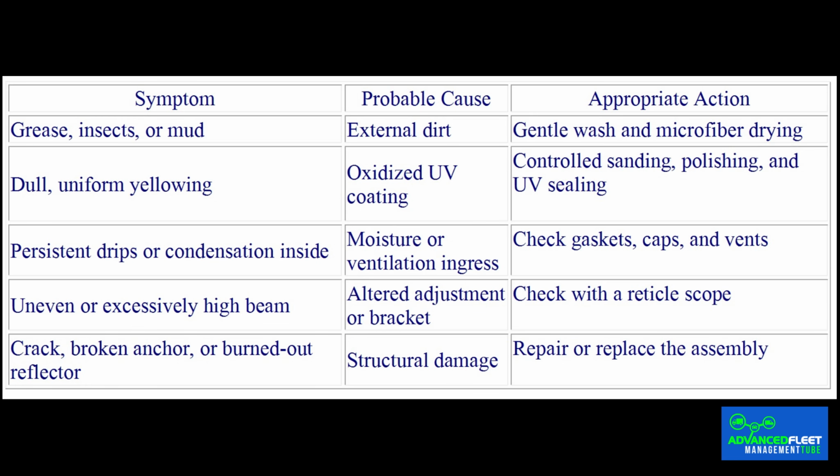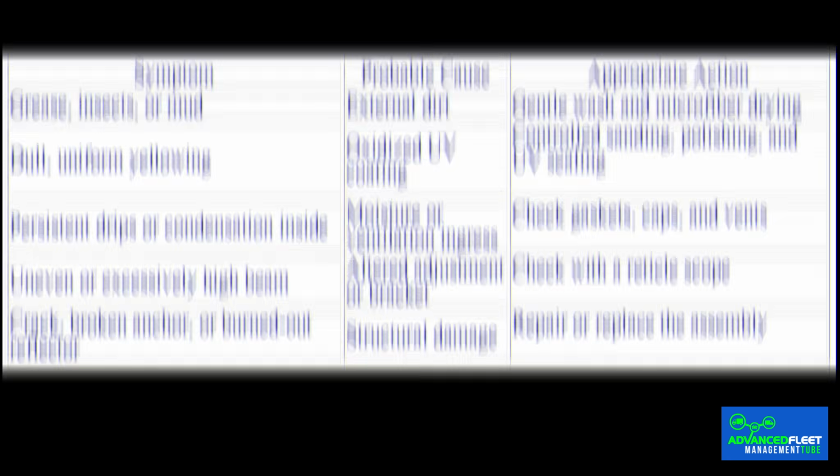It's important to note that imperfections on the inner surface cannot be removed by polishing. Persistent condensation may indicate a problem with the gasket, cover, vent, or housing. The guide to removing moisture from the headlight and locating its source helps distinguish condensation from external cloudiness. In case of structural damage, it is recommended to visit a specialist workshop for a detailed evaluation. The following comparison avoids applying an inappropriate solution.